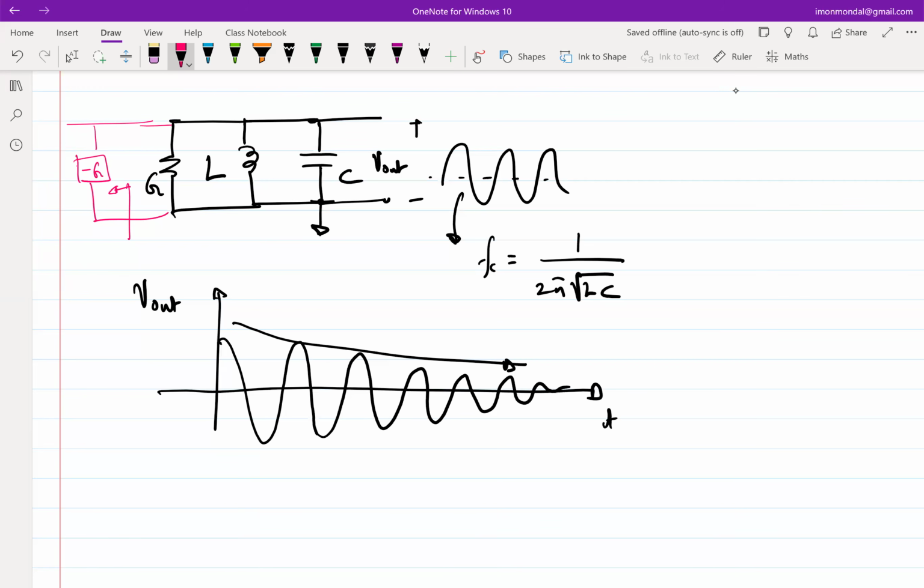So clearly, neither R, L, C or any combination of that can generate it, because if you think about what negative impedance or negative admittance means, if you put in some voltage, it is going to generate a current in the opposite direction, which means it is going to give you back power. It's a power generator, which means that none of these passive things will be able to design that. You will not be able to design any power generator using passive elements. So you will require some sort of actives.